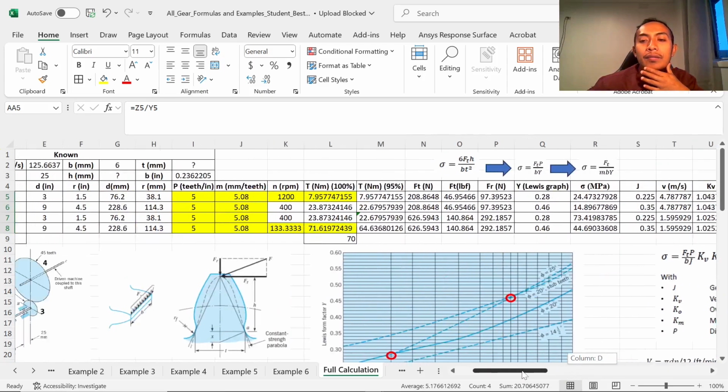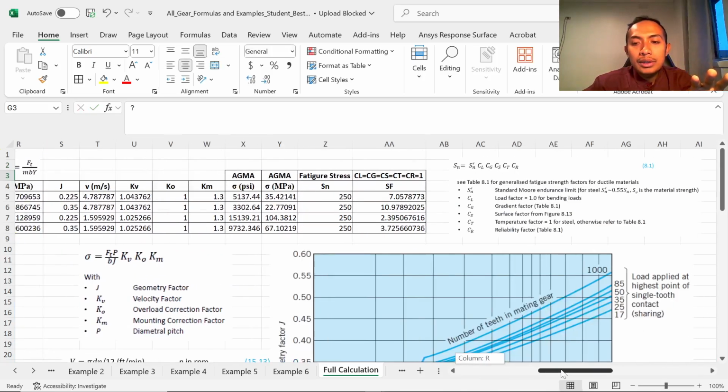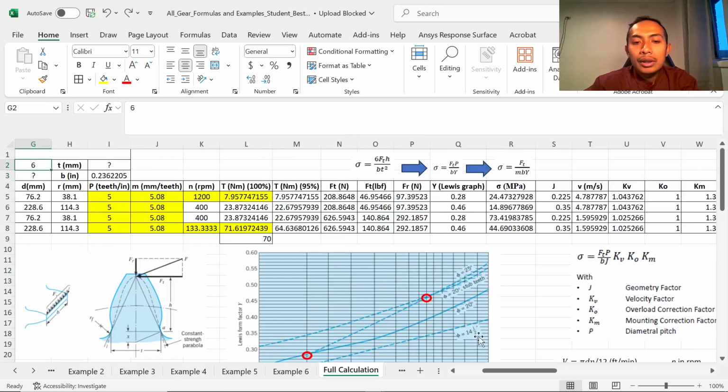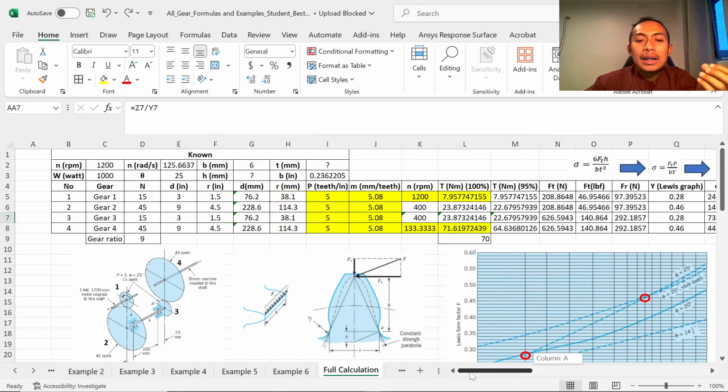The good thing is there are simple things to do to improve the safety factor. You can increase the b, for example, we increase it to 7, and if we redo the calculation, the b1 is critical, so it leads straight to an improvement in the value.